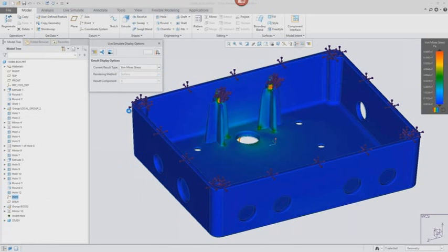See if that deformation is acceptable, see if the von Mises stress is going to be acceptable. It allows me to explore all the different what-if scenarios that come with the changes that I would make to try to reduce those certain parameters. The best part about this extension is that any engineer can really use this to get a better idea of the performance of this part. I wasn't doing some crazy high-end type of analysis that only an expert is going to understand how to set up and run. That was just a very simple, first stab at this problem early in the design phase to see if I'm making smart decisions as a designer as I'm going through and modeling this.